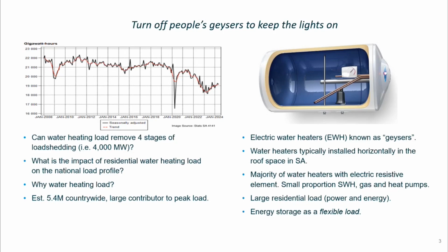We know that the geyser is a large residential load, and I just wanted to mention it's a large load in terms of power and energy. So you've got 3 kilowatts or 2 kilowatts depending on the size, and then your energy is a significant amount, both standing losses and your usage. And the last point I want to make here is that energy storage is a flexible load.